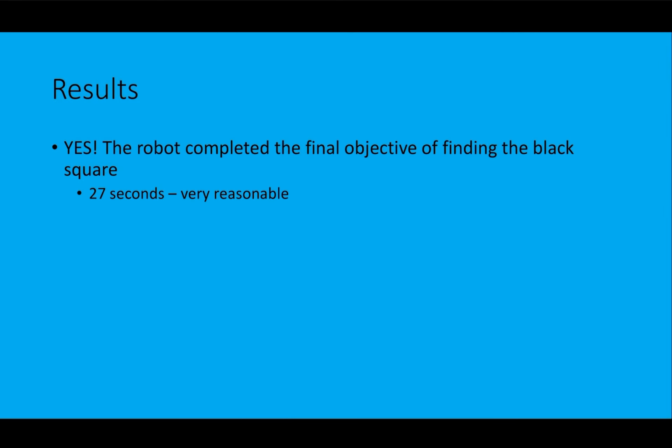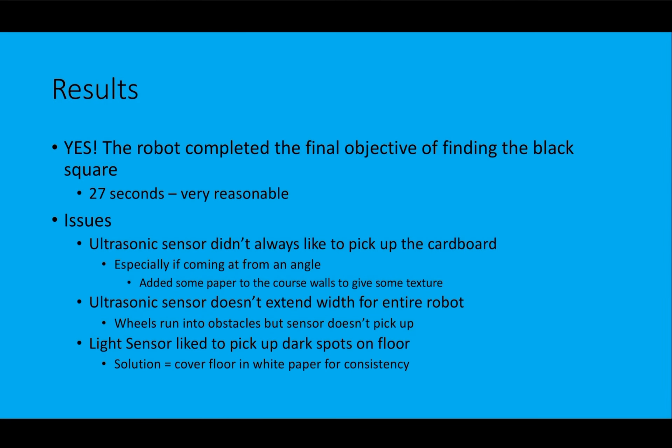And then the results: it was a success. I mean, the robot completed the final objective perfectly fine. It was maybe a little slow, but I think 27 seconds is very reasonable for an 8x8 foot area. Issues: the ultrasonic sensor didn't always like to pick up the cardboard.